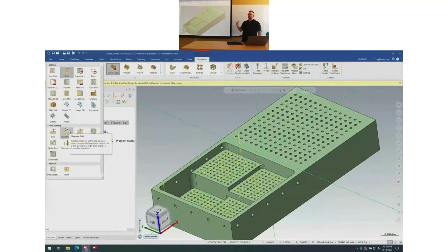Now, in practice, in real life, I would use 2 because I would set up these and this one as a 3-axis toolpath, and then I would set this up as a 5-axis toolpath separately. It's a little cleaner in terms of when it actually runs on the machine and sorting and all that stuff. That's what I would actually do, but you could do it all at once.